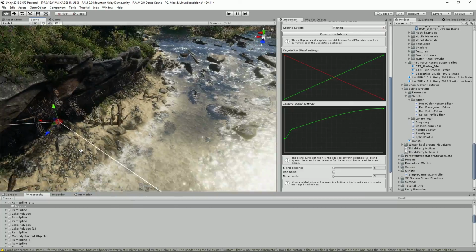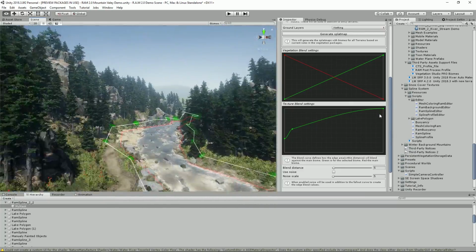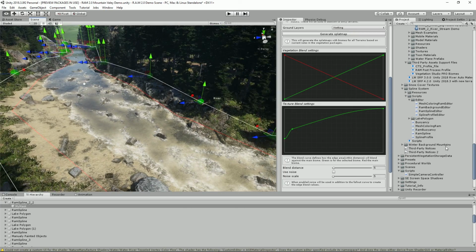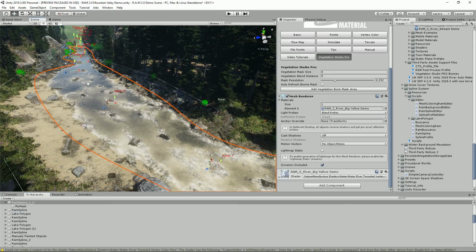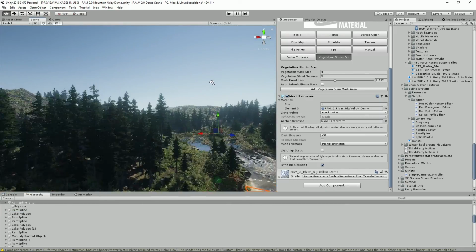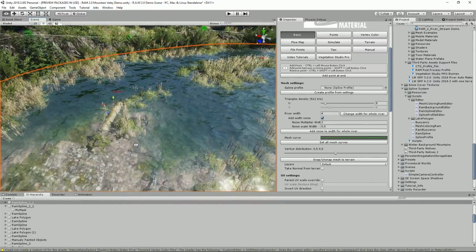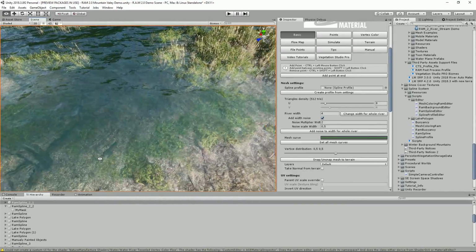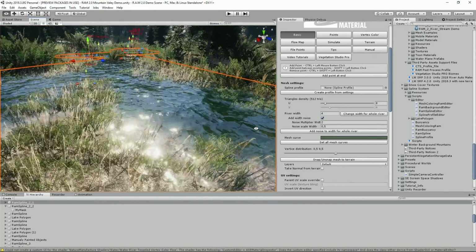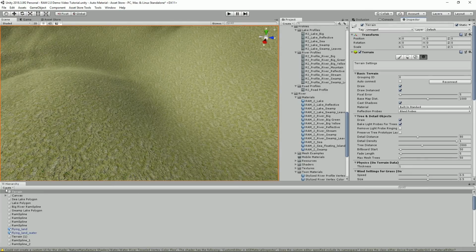All this nice effect comes just because we use high blending from our terrain shader. So biomes and the Vegetation Studio mask are totally powerful tools and give you the ability to create such an environment just out of the box. You simply choose the biome, click generate, and you have whole foliage and textures painted and planted.